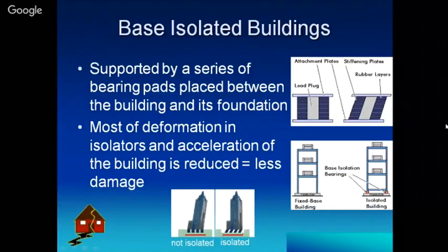Again, base isolated buildings. As you can see, a building without base isolation has more deformation and displacement, as compared to the building with base isolation, which has less displacement. This is the purpose of base isolation, because it disconnects the superstructure from the soil, or I should say it disconnects the superstructure from the substructure.